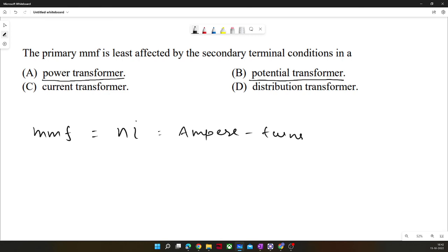You know, transmission lines, where after generation the power is needed to transfer. Generally, we do not prefer to transfer low voltage, high current through a wire due to the obvious reason, the losses. So we always try to transfer high voltage, low current.